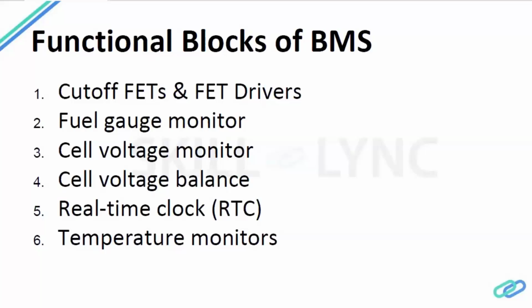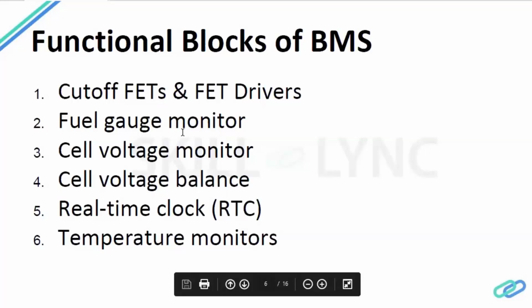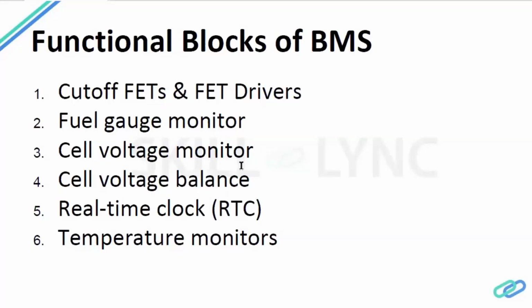Okay, there would be a real-time clock, because we will be constantly monitoring these things, so there should be a real-time clock inside the BMS circuit. There should also be a sensor which can measure the temperature of the battery pack and also the temperature of the battery management system circuit. These are the functional blocks of the BMS which we need while building any battery management system for an electric vehicle, a laptop, or any lithium ion battery pack.